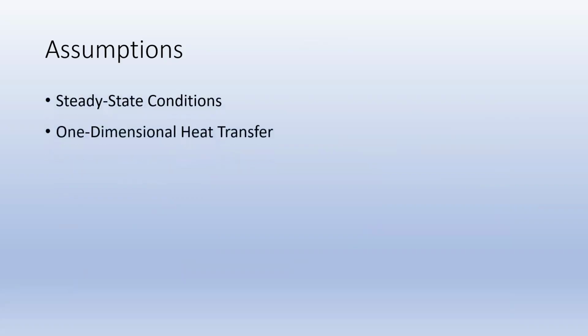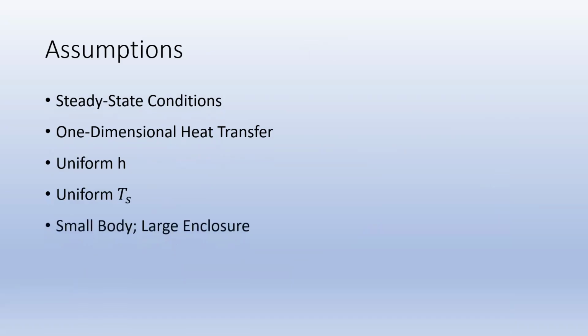Now, before we start solving the problem, we need to state our assumptions. We are under steady state conditions, working with one-dimensional heat transfer with uniform H and uniform Ts. And lastly, for radiation, we have a small body and large enclosure.